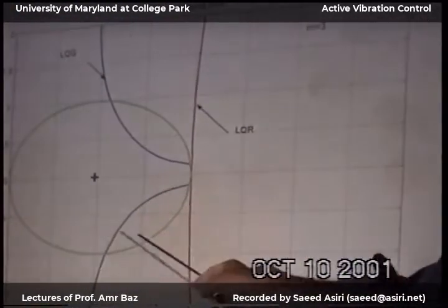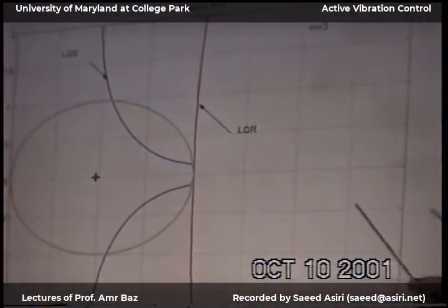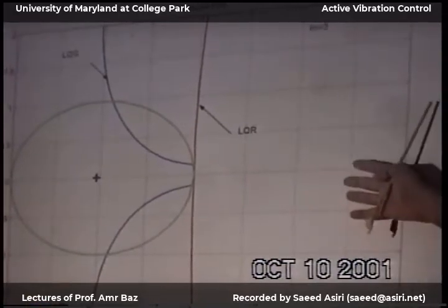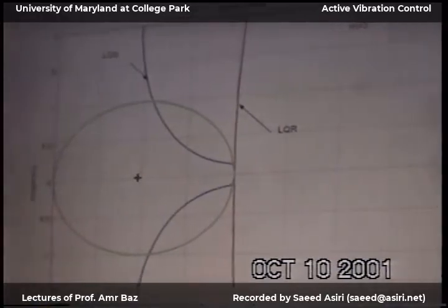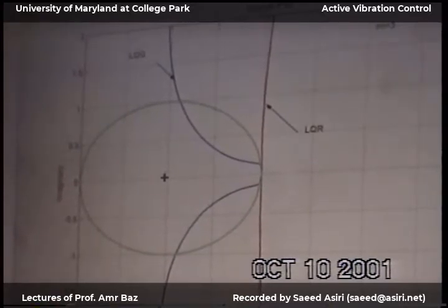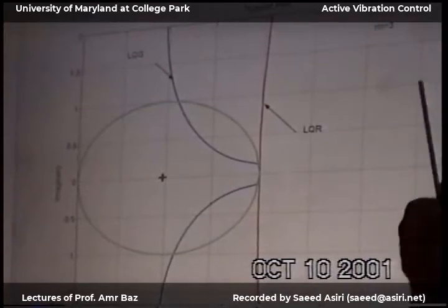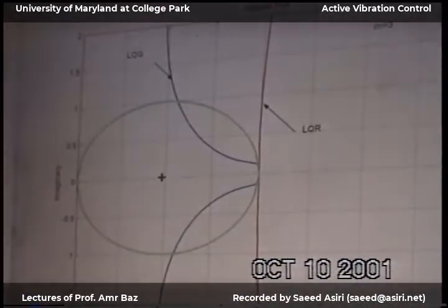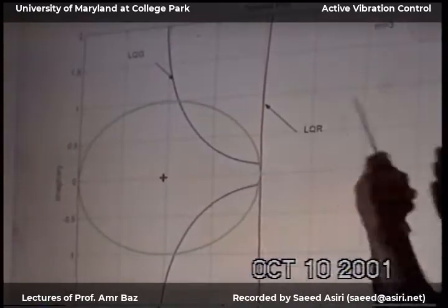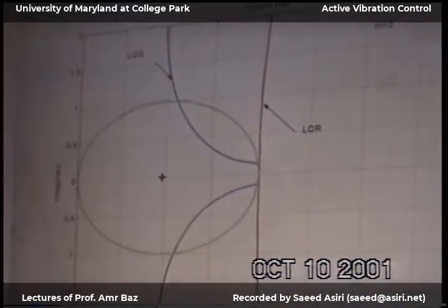More inside. Now how this will be translated, if you have a system that you run analog, that's what you will see. But when you start running the system digital, you are making delays, because you have to sample and wait, sample and hold. You sample and wait, and then you sample again. You sample and wait, and so on. So if the amount of wait is very big, you can create very large delay in the system, and you can eventually hit the 180 degree. The delay will make the system go unstable very fast.